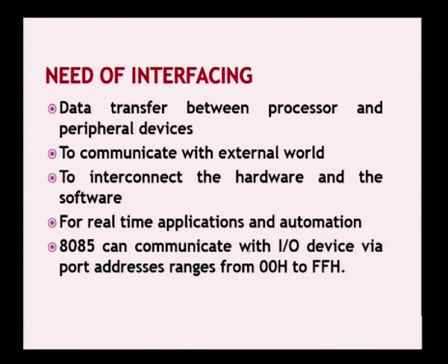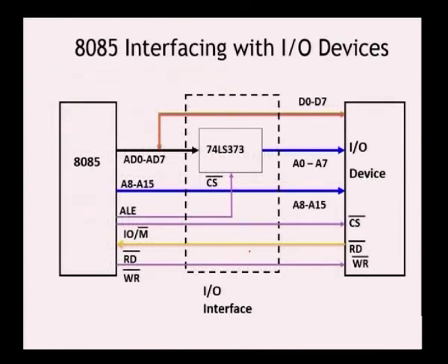To interface the microprocessor with the peripheral devices, we have addresses 00 to FFH. From these you can select any one address. This diagram shows simple IO interfacing with the microprocessor. First we have to select the address and data. For any interfacing, you have to draw 2 boxes, then give the required signals or the operations. So, we are giving the address and data lines.